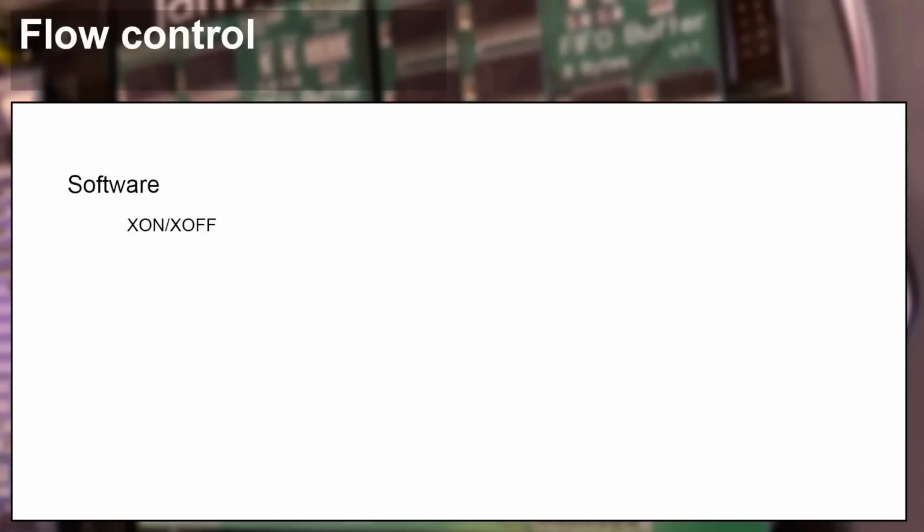Now in this case, the receiver needs to be able to keep up with the data when it's focused on it, either directly or by monitoring a receive buffer, and it needs to be able to intelligently tell the sender when to stop. So this wouldn't really solve the problem of not having the CPU performance to keep up with the incoming serial data, but a common use case for this would be a data transfer program asking the sender to stop because it had to switch attention away to write data to disk or perform another task.